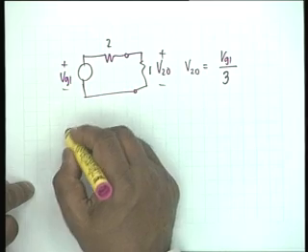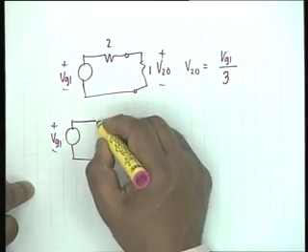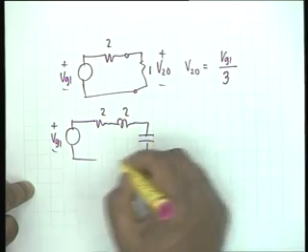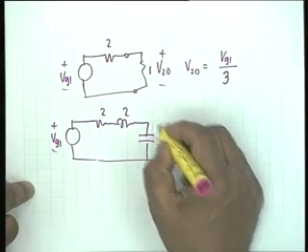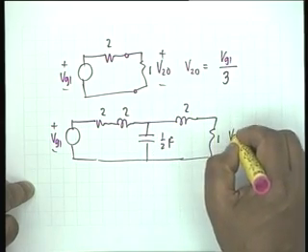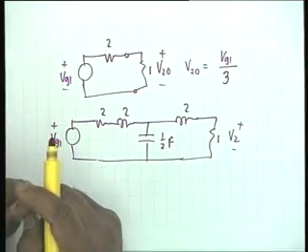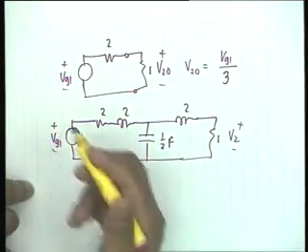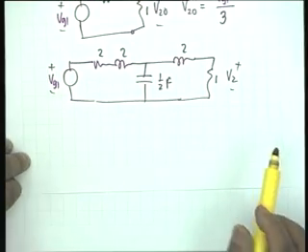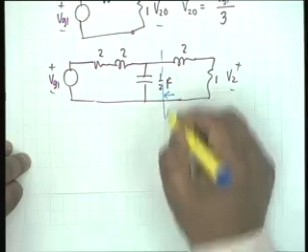Then you have to find out V2. Okay, for finding V2 you go back to the network. Vg1, 2 ohms, 2 henries, half farad, 2 Henry, 1 ohm, and this is V2. You have to make an analysis of this network to find out V2, and the way I find it convenient is to apply Thevenin's theorem, that is to the left of these lines.